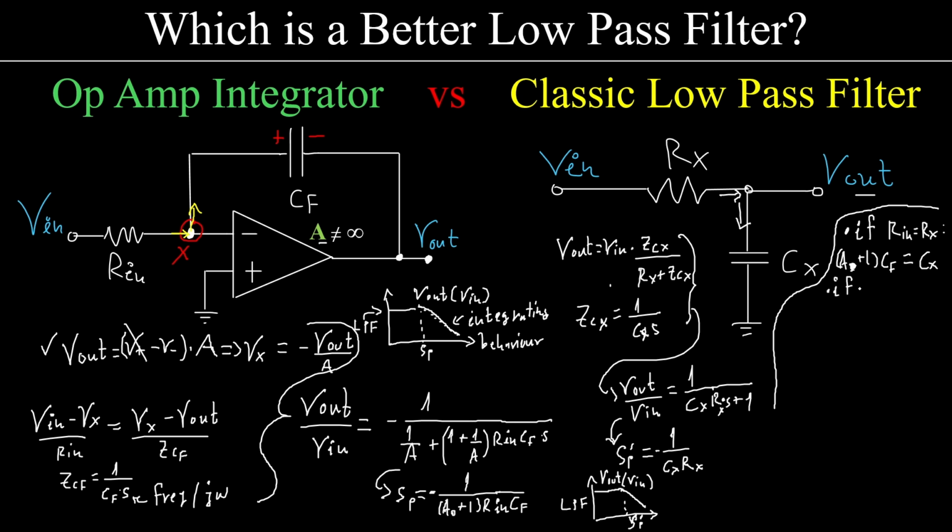Again, if we try to work similarly and say CF was equal to CX, we see clearly that for this resistor to be close to this resistor for the same capacitor value, it would have to be 1,000, 10,000 times higher. We would have the same capacitors, and this was, let's say, 1 kilo ohm, alright?